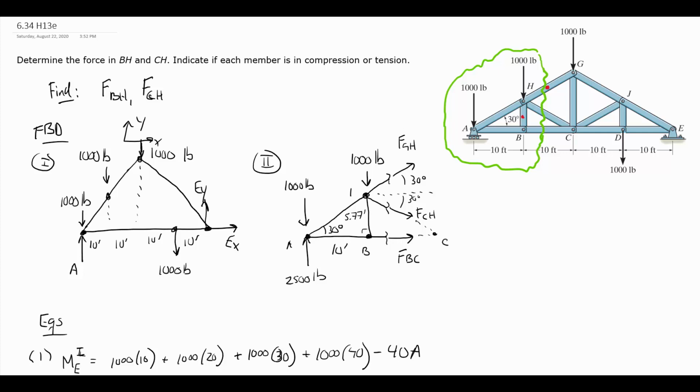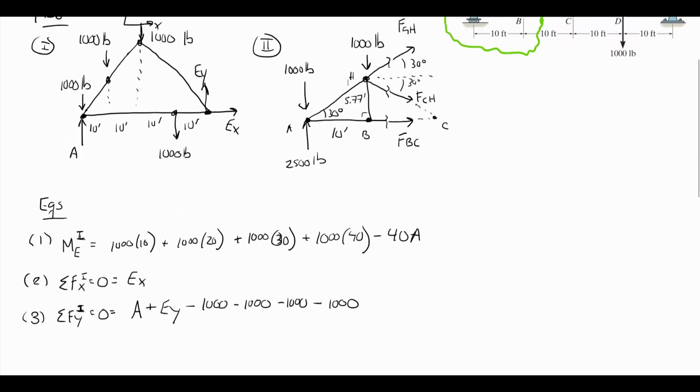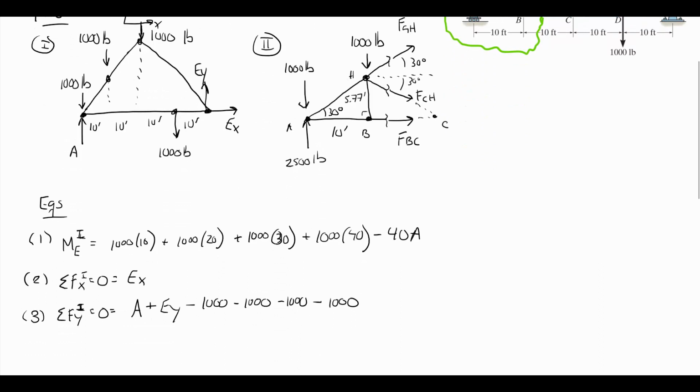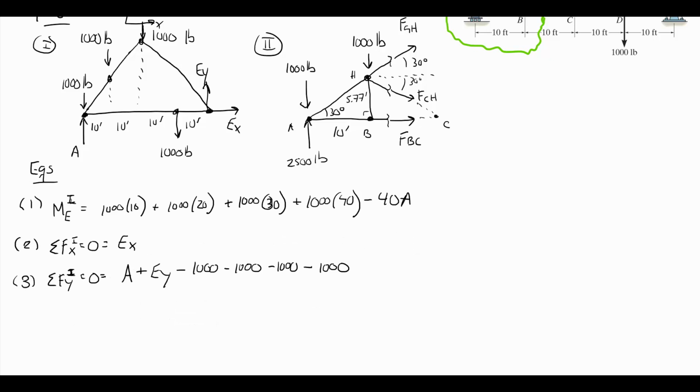All right, so we have this complete free body diagram. I'll put in the rest of these labels here so we can refer to them. So my free body diagram 2, again, by design, we see that there are only going to be 3 unknowns. Because it's a 2D rigid body, I will be able to solve for all 3 of them. So using picture 2, I can write new additional equilibrium equations. In picture 2, I am going to start by taking the sum of moments around H.